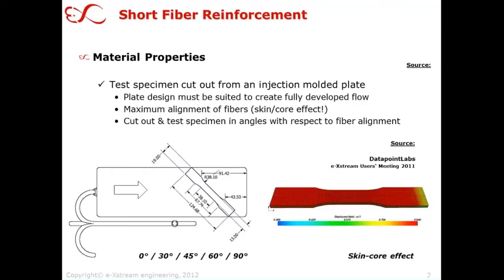And this is exactly what you test if you take the second approach that we look at on this slide here. So of course you can injection mold a plate, quite similar to what I have shown on the first slide, and then it's a plate which is dominated by the fully aligned flow.